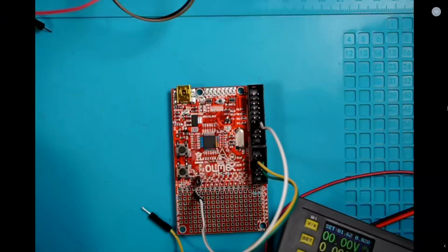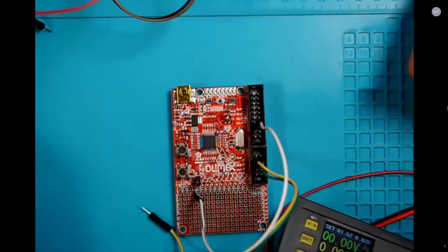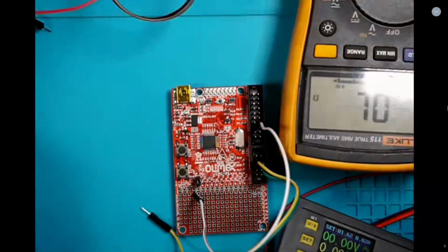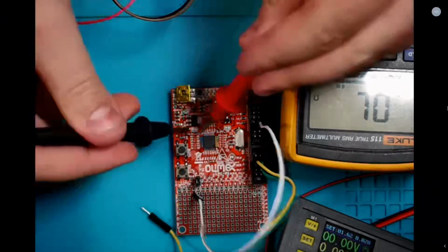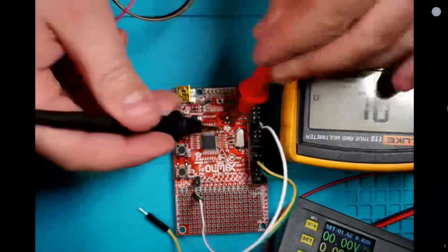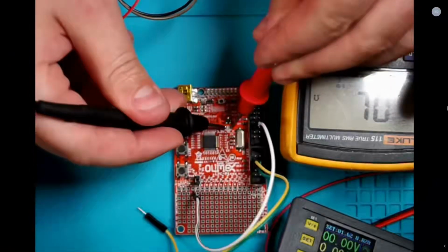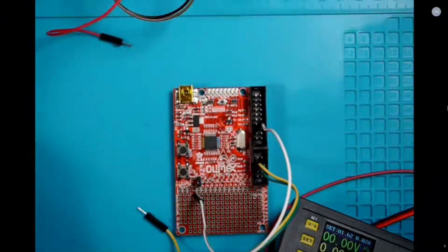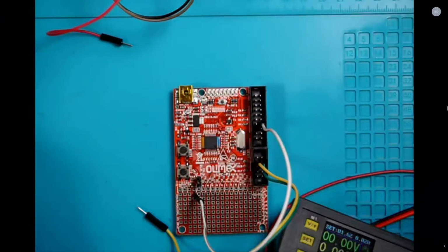So let's do it. I'm going to take a knife real quick. Let's also use the multimeter that I have right here. We're going to go into continuity mode and check that the connections are still there, between this guy and this guy. Hopefully you can hear the beep on the stream. It's beeping, which means there's a connection there and there. So now let's cut through those, and we'll have separated the power supply from the rest of the board.